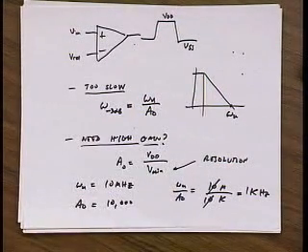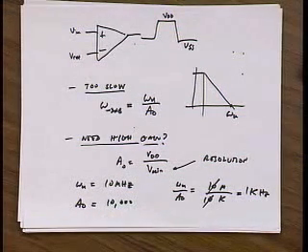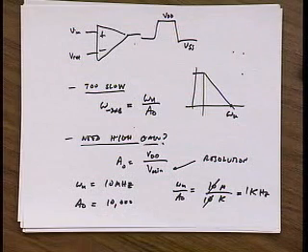You can actually buy op-amps designed for high-speed applications. What are some of the other issues? I'll give you a hint. If I have a gain of 10,000, does that mean I automatically get 100 microvolts of resolution?